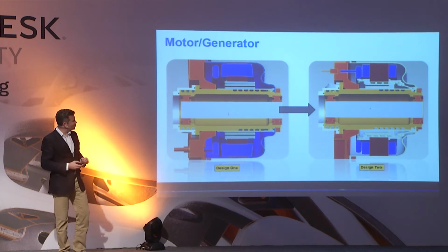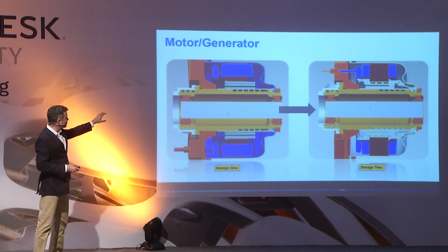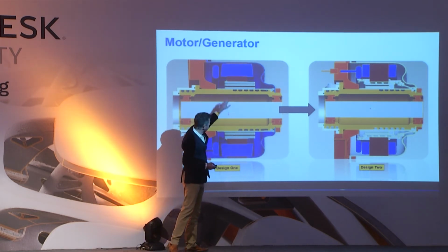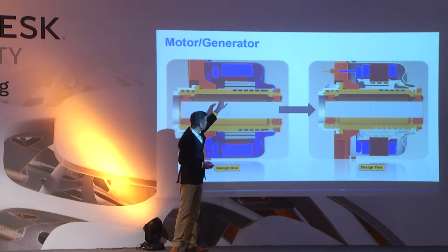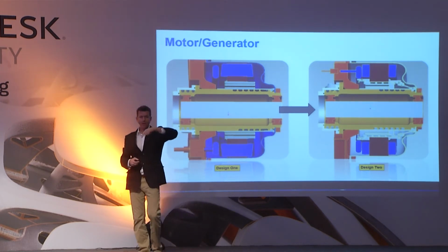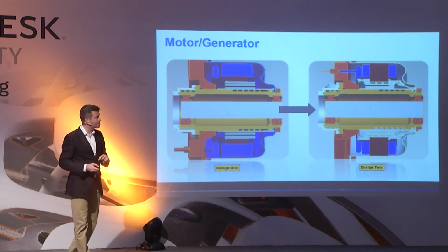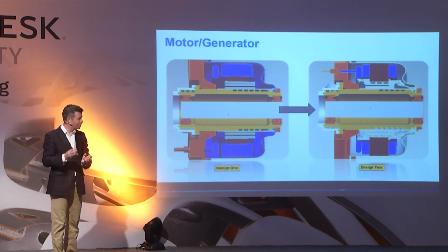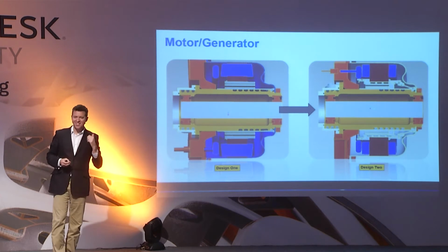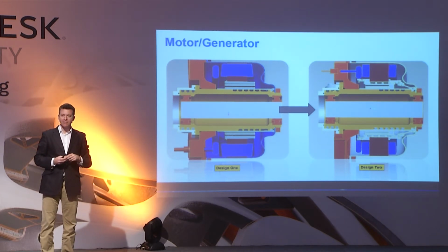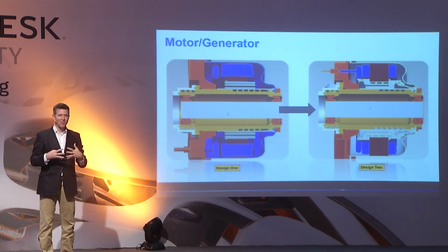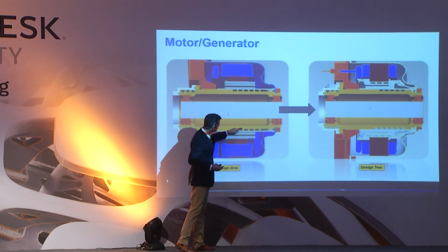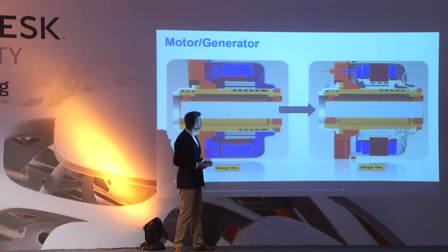So what you're seeing is a cross-section through the design where we have the actual generator, and this is basically an iron web, around which you have copper coils for collecting the energy. Now, the problem with this is that there's a huge amount of heat going into these webs of the core. And so this is actually liquid cooled. So we're mixing water with electricity, which I'm sure is not a good combination. But we have water going through this cooling channel here to try and cool these windings.